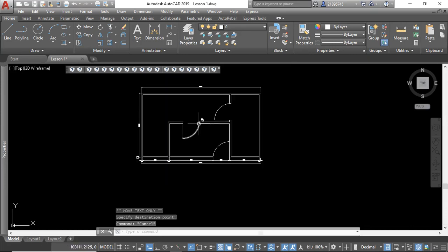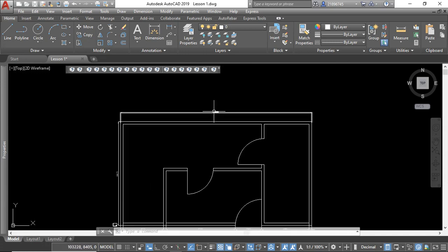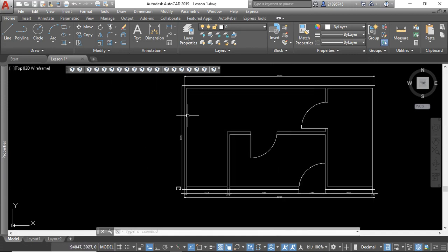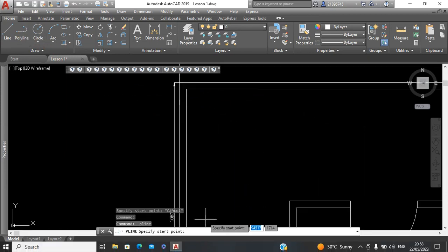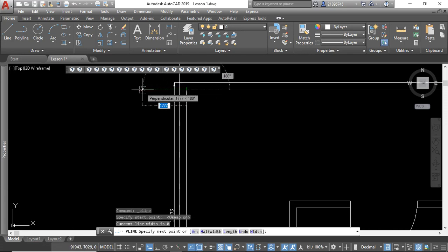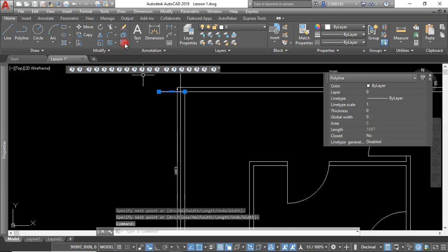and the other thing I can do is, maybe I want to also have a window here. So just by doing the presentation indicative, I just hit the snap button, I can draw a line like this, and maybe I want to offset my window from the wall to some distance.